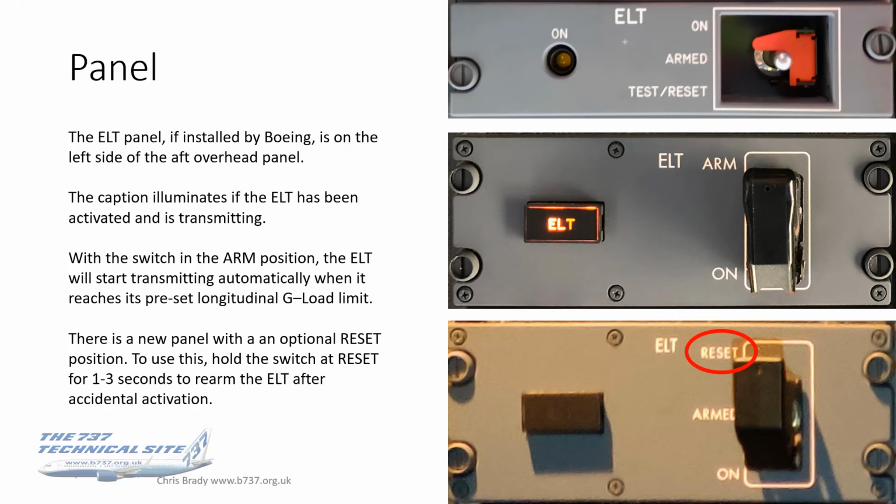The ELT caption or light on that third-party STC version is just a light. That will illuminate if the ELT is being activated and is transmitting. So if that's on, then it shouldn't be. You need to get that switched off as soon as you can.